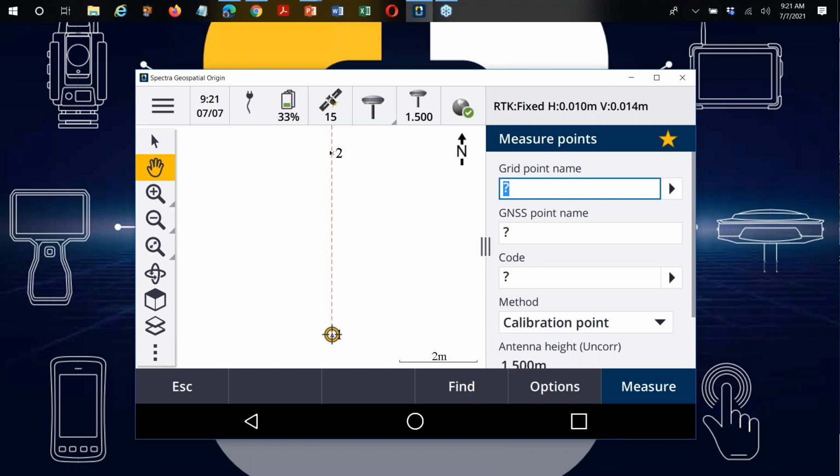I will say one thing that affects a lot of people in North America. We use a lot of ground-based assumed systems. And in Survey Pro, when we would do that, we would use an oblique stereographic projection to go from grid to ground. And inside Origin, they use a transverse Mercator. Maybe I might be mistaken, it's either a Lambert or a transverse Mercator. It's not very important unless you're on a very, very large project that's using ground, but it is a point to consider that at the edges of a coordinate system localization like that, there might be slight differences.